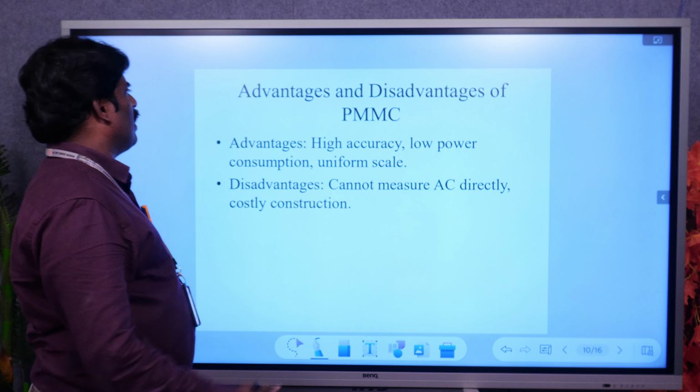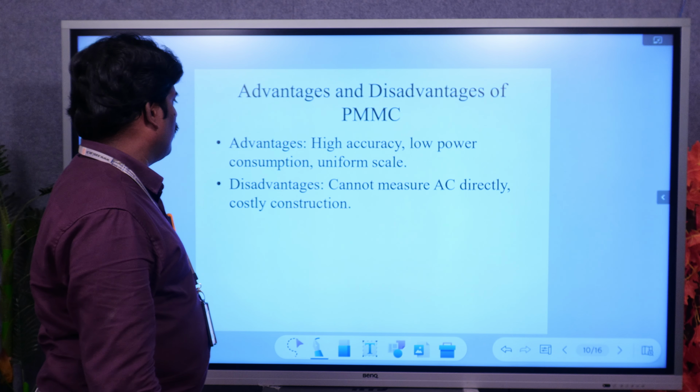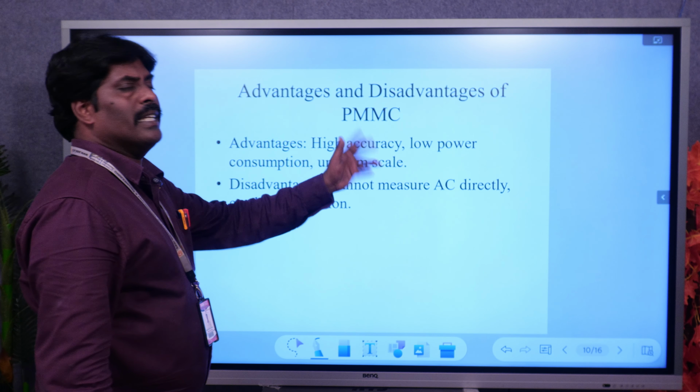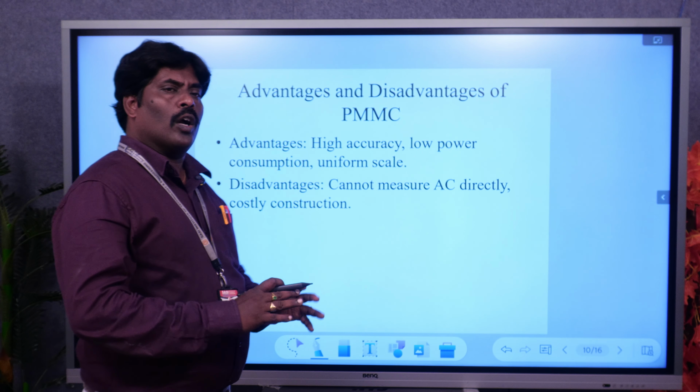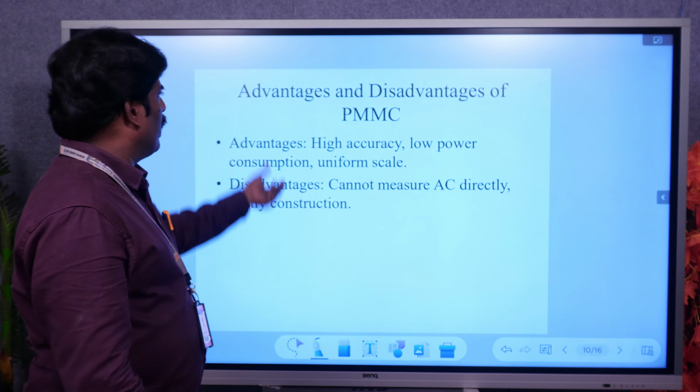Advantages and disadvantages of PMMC. Advantages: high accuracy, low power consumption, uniform scale. Disadvantages: it cannot measure AC directly, and it has costly construction because springs are costly, so it will be expensive.